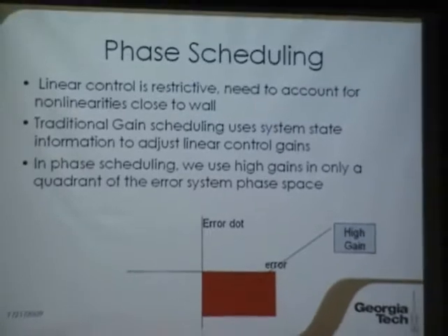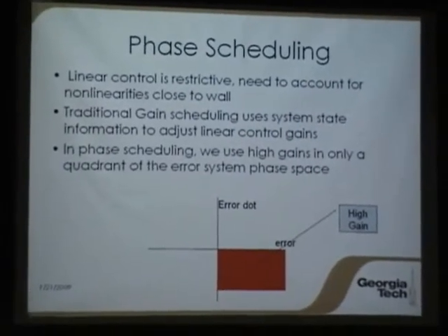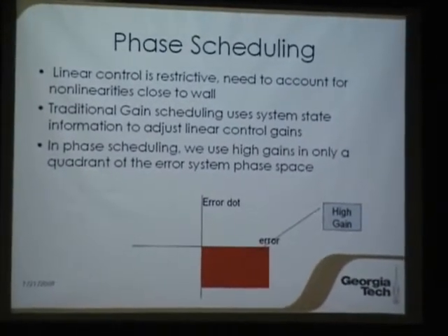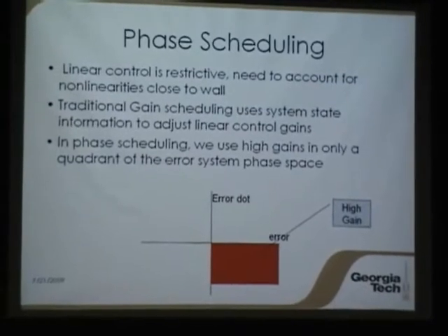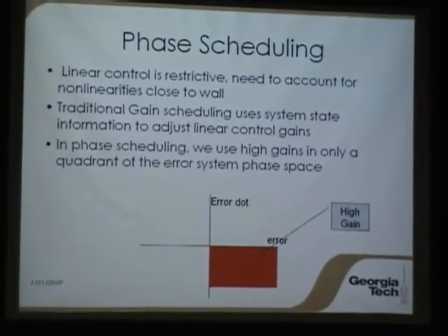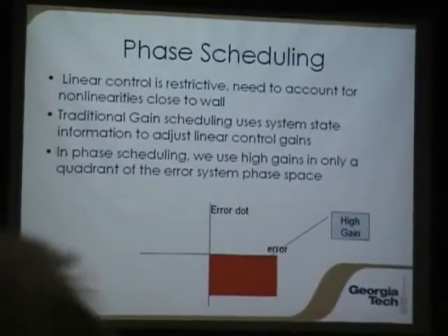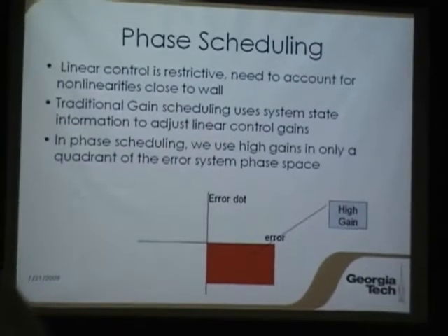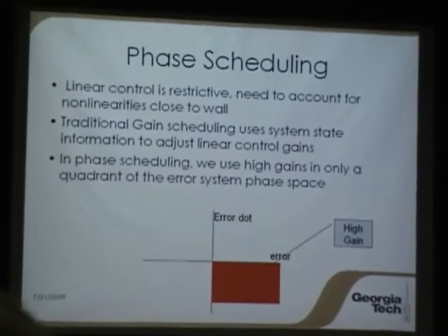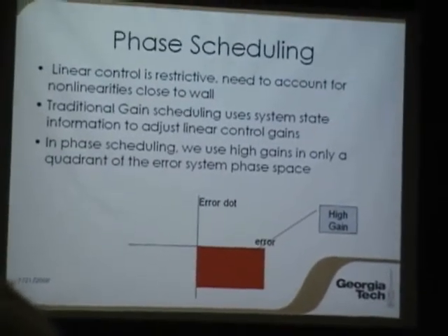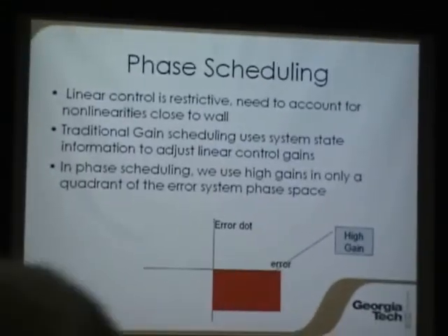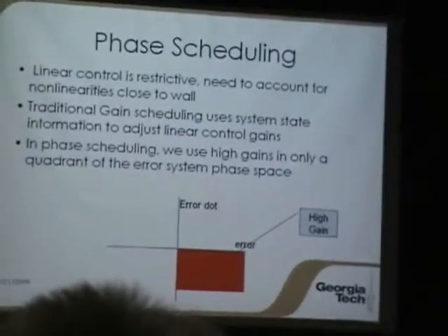So, alright, suppose we have this Kalman filter that gives us relative velocity to obstacles. And we have the vehicle that is following walls, which is actually of the coaxial type. When you're close to walls, the rotor inflow from the vehicle interferes. The wall interferes with the rotor flow, and that creates some kind of non-linearities.